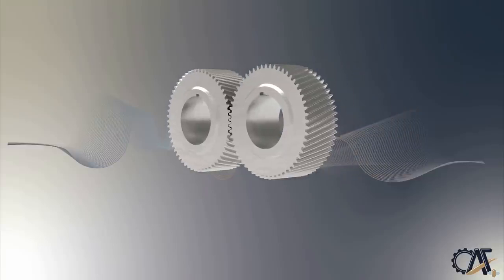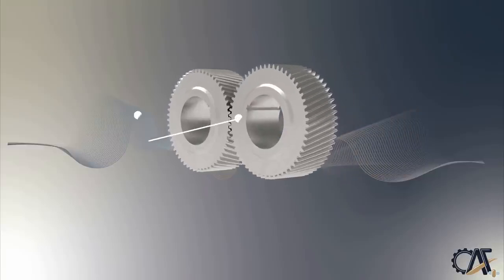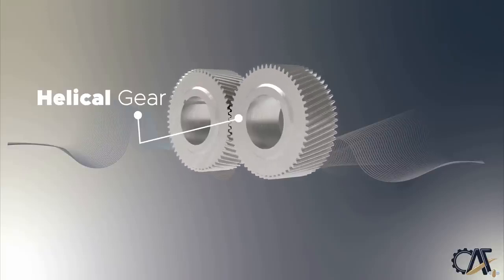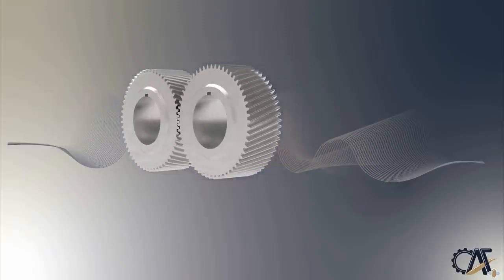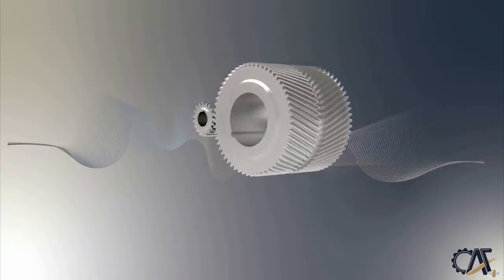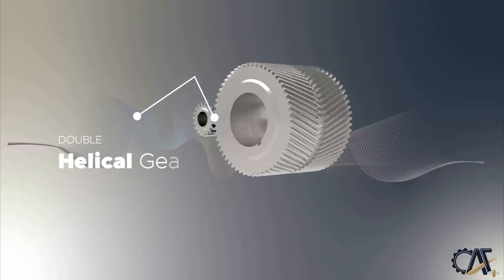Helical gears are used with parallel shafts similar to spur gears. However, helical gears have teeth that are oriented at an angle to the shaft, unlike spur gears which are parallel. This causes more than one tooth to be in contact during operation, and helical gears can carry more load than spur gears. Due to the better teeth meshing than spur gears, this makes them a better choice for high-speed applications. Also, they operate smoother and quieter than spur gears.